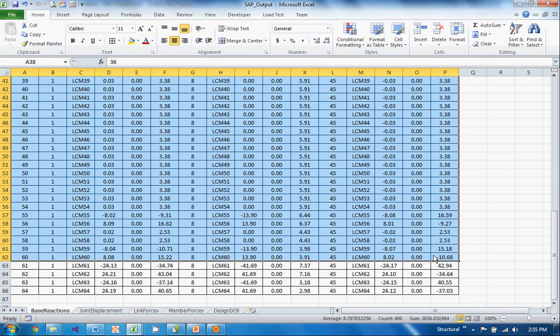So when we're doing a footing check, checking shear and bending in concrete, these are LRFD. When you're checking moment and shear, these are LRFD. When you go to the bearing pressure for the footing, that's ASD. For foundation design, that's ASD. If the moment frame is located on the podium, it will be with the LRFD.